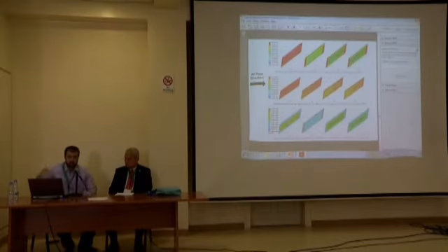This is because the coil temperature in this case is not uniform. We have refrigerant entering in this direction at a certain temperature and air crossing like this, so we will have a change in temperature. So the dew point temperature will change, and accordingly we predict non-uniform condensation rates. This appears in the second row of figures.